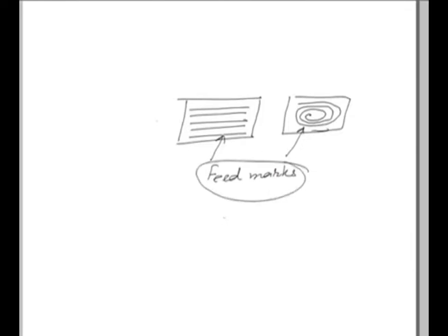The AFM process is capable of removing the scratch marks produced by other machining processes. As we know, in most of the conventional machining processes, scratch marks are produced like this, what we call feed marks. If it is a milling process, then the surface will have some kind of textures, something like this, or it can be something like this, depending on the process. These kinds of marks, which we also call feed marks, are nothing but results of scratches of the conventional tool.